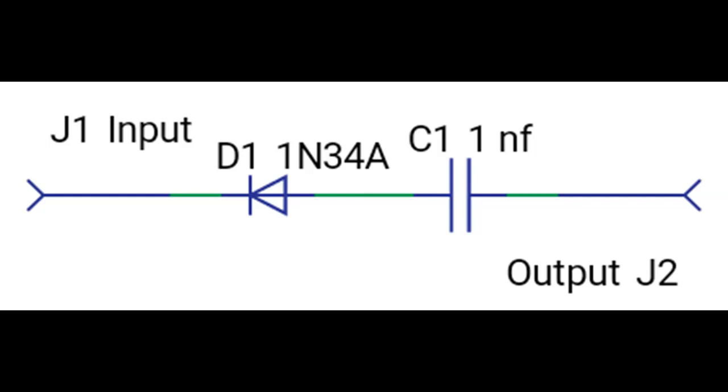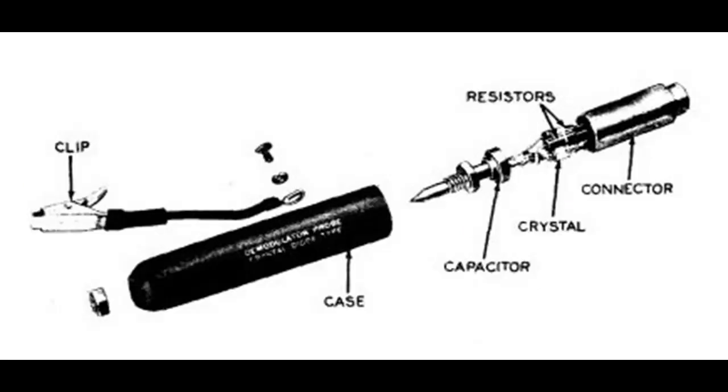Well, we've tried using that in the past, and I tried it again, up at the end of the coax, and it reintroduced our distortion problem. So I started looking around at different designs. I saw this one here. This uses a resistor divider and a crystal diode. I tried that. It was still distorted.